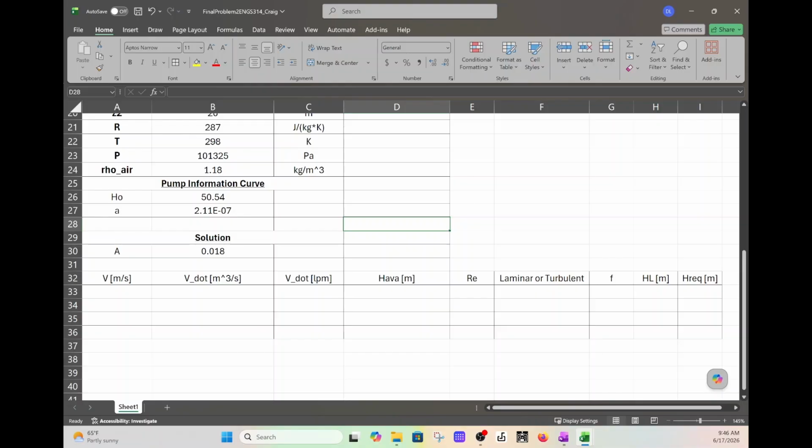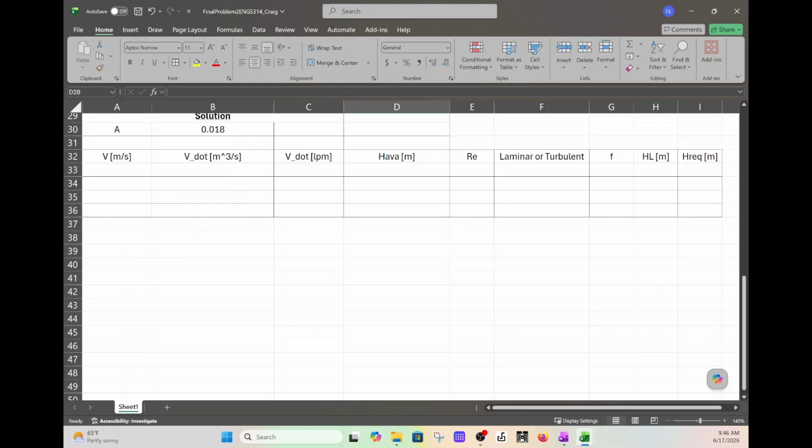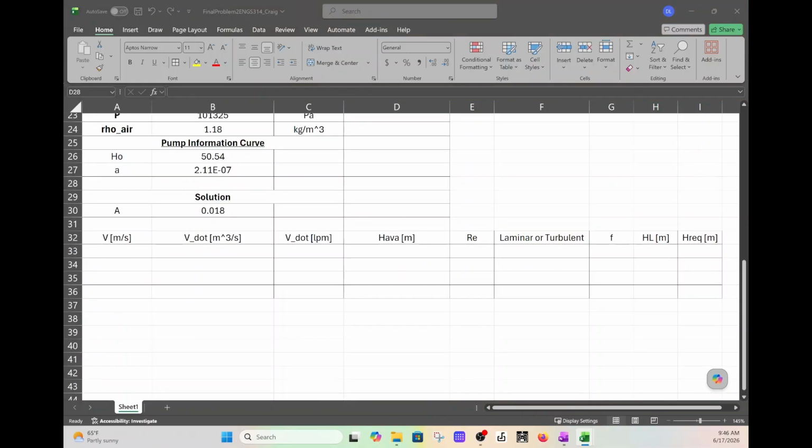All right, okay. So what we're going to do is, what did I end up doing? I went 0.5, sure, okay. So let's just start with 0 for now. And right now, in cell A34, put equals, click on cell A33, and hit the plus 0.01 for right now. Then you hit enter, you go back in cell A34, and you can left click and drag down a few spots.